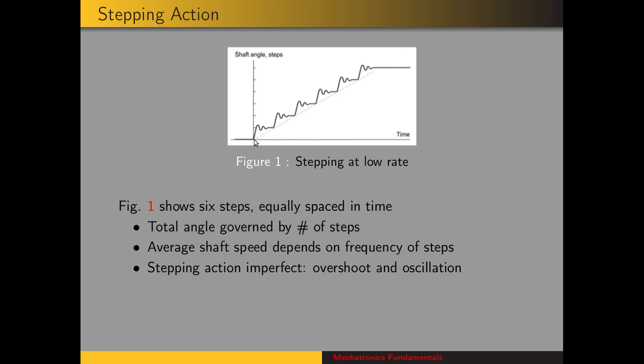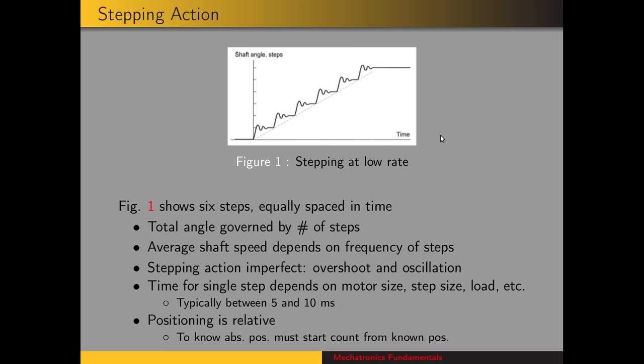And we also see that the stepping action is imperfect. There's some overshoot and oscillation with each step. That oscillation time, or the single step period, varies depending on the motor size, the step size, the load, etc. And it's typically on the range of 5 to 10 milliseconds.